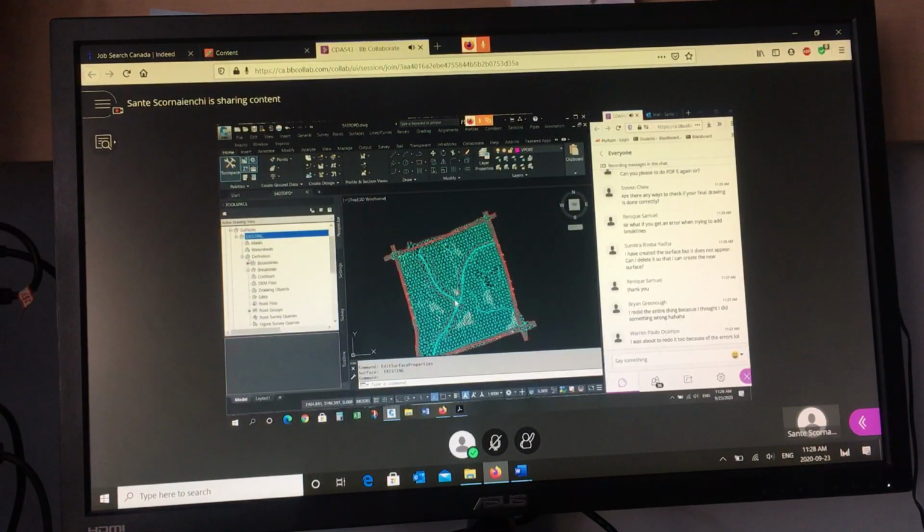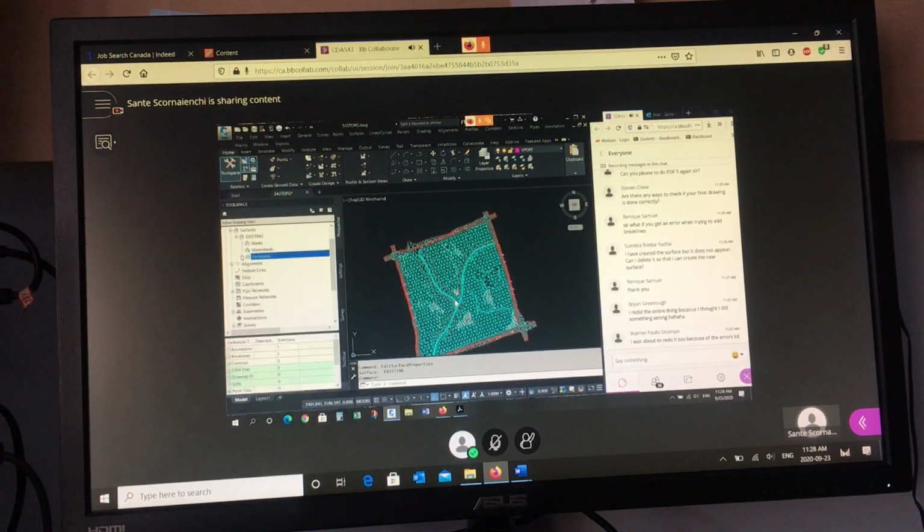What I do is this. If you defined the groups, which in your case should be all the G' groups, I didn't do that, but you should have your groups here. If that group has nothing in it, then it won't build anything. And here's the trick. Here's what you want to check. If you say to the surface, use the group to build the surface, and there's no points in the group, you're not going to get a surface.